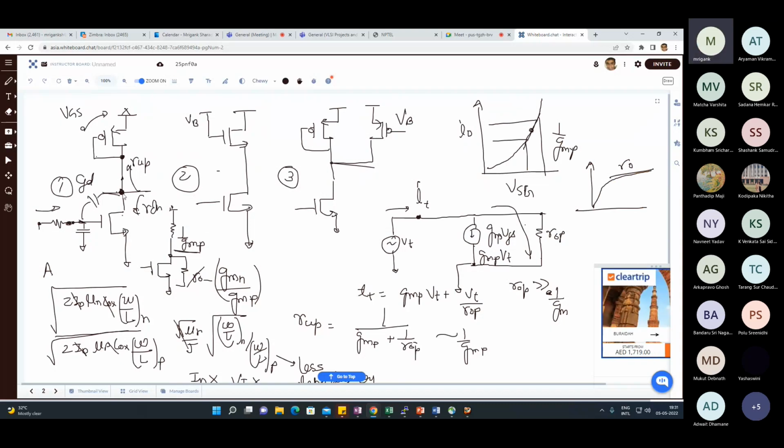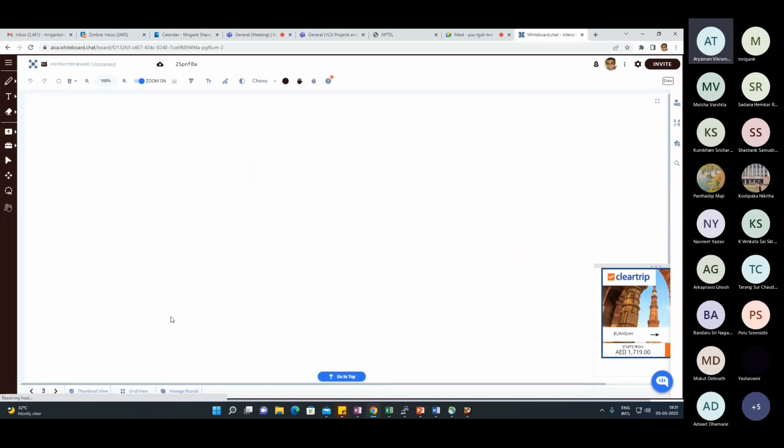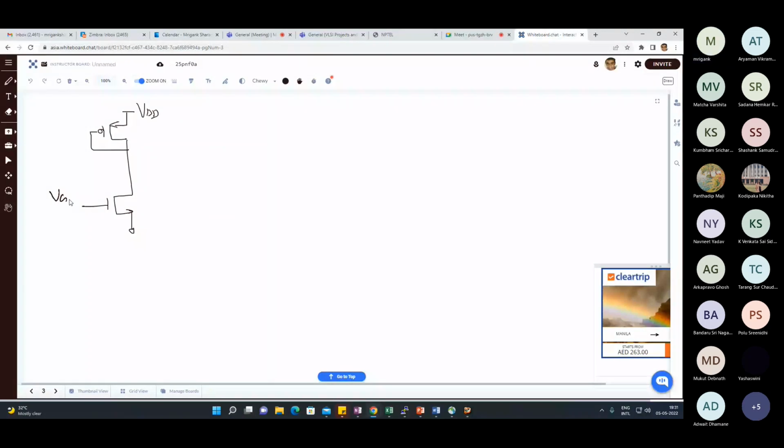Think about it a little bit better. Upper limit, lower limit means what? You can go to VDD, or 1.2 VDD, or 3 VDD. The lower limit would be the bias voltage you are applying plus the threshold voltage. No, the upper side: of course, this PMOS transistor has its source connected to VDD, and the lower side has this condition. Now this is VDD, and this is whatever VGN you have applied, for biasing from the previous stage.